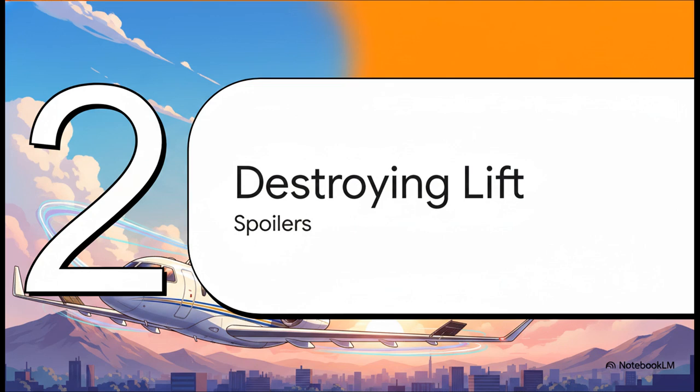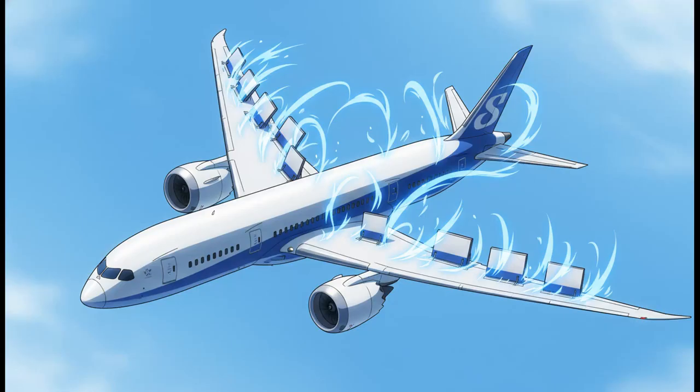Destroying lift. Sometimes you just have way too much lift and way too much altitude and you need to get down. Enter the spoilers. Spoilers deploy straight up from the top of the wings to purposefully ruin or spoil the smooth airflow. This instantly kills lift and spikes your drag. If you pop them on both wings at the same time, you can dump altitude fast without gaining excess airspeed. Pretty handy, right? But on many aircraft, they also work asymmetrically for roll control.